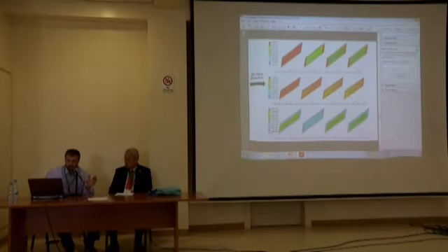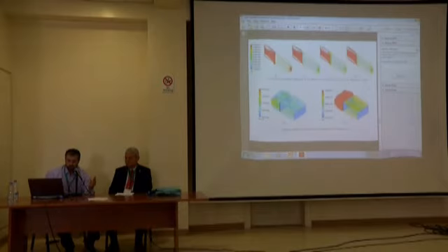The last row of figures shows the velocity magnitude contours also as air crosses in the axial direction. Anyway, you can visualize any property of interest to you and analyze it. Here, for example, I used XY planes at different Z positions, and you can also look at the flow vectors colored by, for example, temperature. So you can look at how the velocity changes with temperature. You can also rely on 3D, of course, for example, to inject some path lines to see how the properties, velocity and temperature, change.